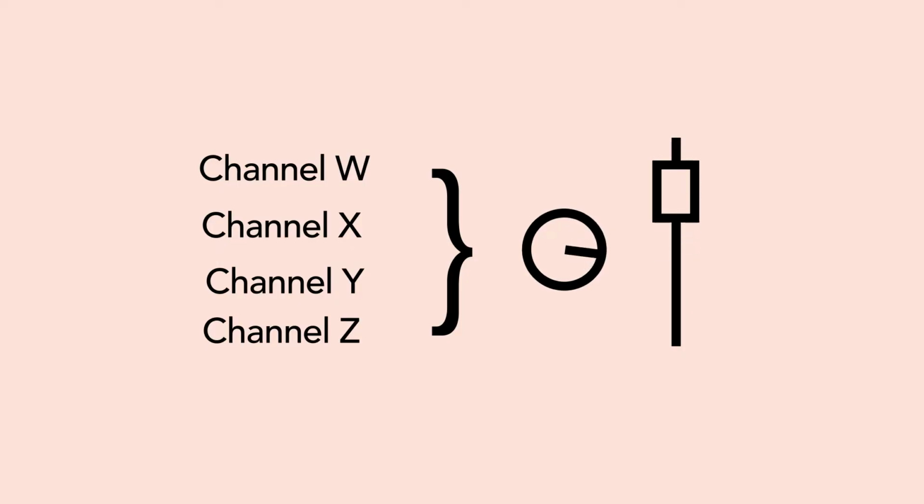We're trying to get our recorder to within 1/10 of a dB from channel to channel. In order to do that, you can easily use pink noise or any other kind of test tone to accurately calibrate those signals. Whatever you decide to use as your signal test tone, as you set your gain staging for your preamps, you're going to want to make sure and leave 12 to 16 dB of headroom so that as your performance happens, you've got room for dynamics.